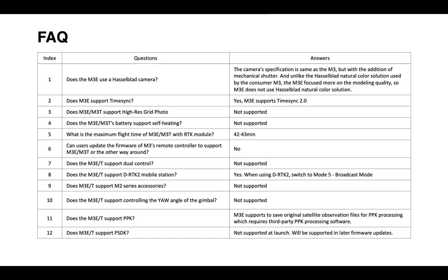DRTK2 mobile station is supported. You put that in mode 5, broadcast mode, to connect to the Mavic 3 Enterprise series. I think that covers most of the questions, and a few of those are review from earlier slides as well, just important points to note.